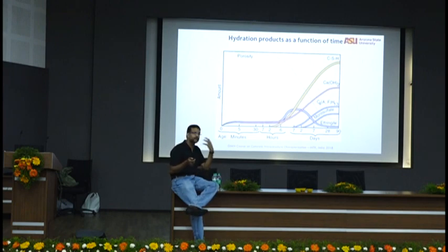Both crystalline products love surfaces. They go stick to surfaces. Surfaces typically are aggregate surfaces, sand surfaces. When they go and stick on sand surfaces, then the corresponding CSH that's forming will have to form in the remaining space. Naturally, very close to the aggregates, you will have more porosity. You don't have to create a new theory for it, like a lot of people do. Right? A lot of people come up with a lot of crazy theories of why there is interfacial transition zone.